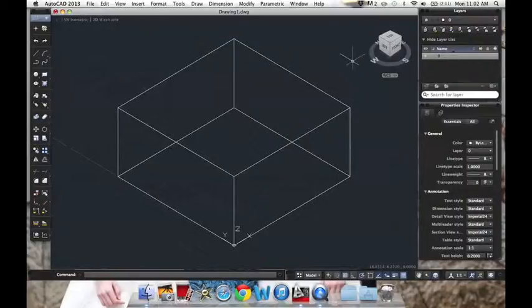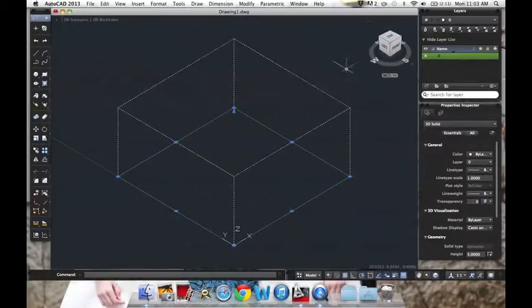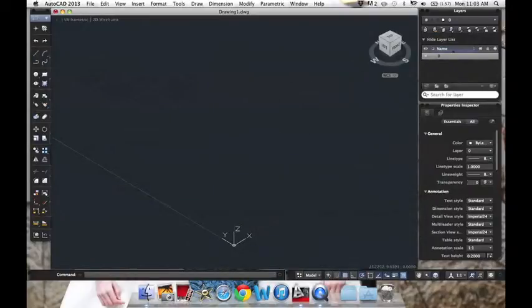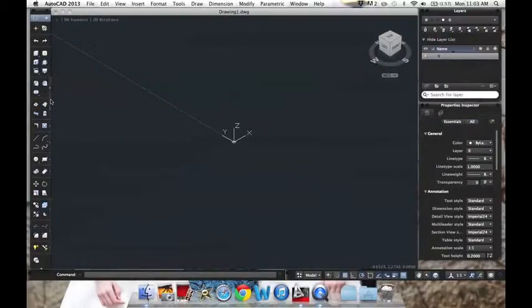There is another way to make a rectangular prism, and I'm going to show you how to do that right now. So we're just going to delete that, get it out of there. This time we're going to go to modeling. With modeling, you don't have to use extrude and everything because it already makes a three-dimensional box. See, create a 3D solid box. So we're going to click right there on that. And for the first corner, it's just going to be the origin again. So 0, tab, 0, enter.